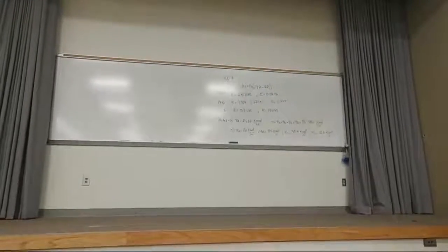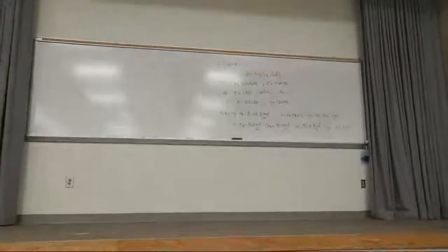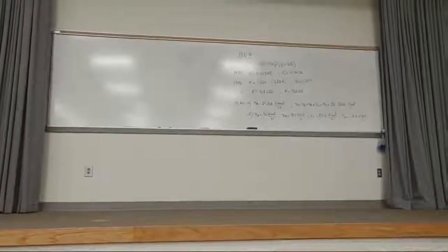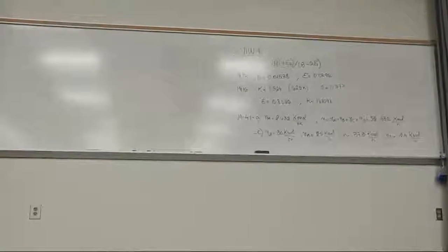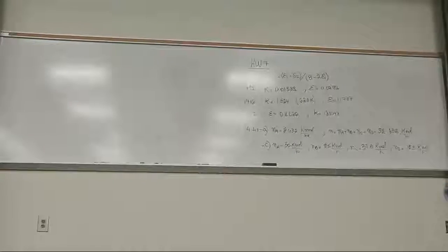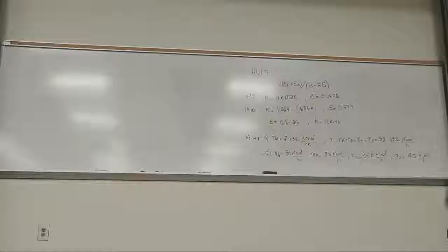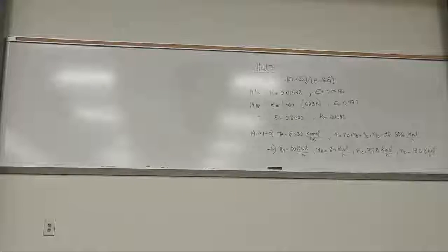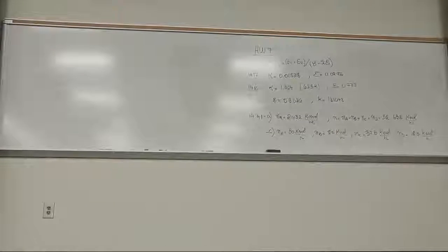Discrete digital, or I should say in the discrete domain. But there's a simple transform. It may be termed different things. It's a bilinear transform where you can actually take a function in H of s and, by a little sleight of hand, find the translation between s and z and then create a function in z. Now remember, z is discrete time, that will implement that same filter action in the frequency domain.